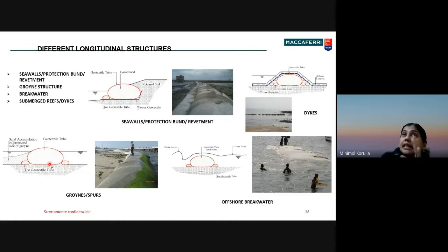So, before we go to the case study session, I would like to introduce certain other building blocks. I introduced the Gabions, reinforced soil systems. Then we talked about the debris flow barriers, steel barriers, drapery system. So another system which can be used for protection of slopes is geocontainers. Using polymeric products, we can create big geotextile tubes or bags. You might have already heard about the geotextile.